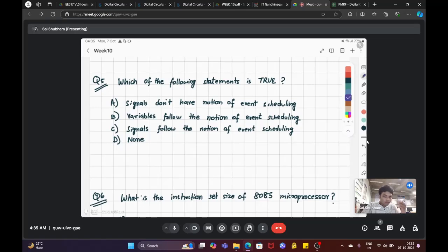If you want those operations to be iteratively performed over multiple cycles, you can use variables. You can define a variable i that is equal to 0 and iterate for multiple cycles. So in that case, there is the importance of variables. You cannot take a signal and iterate it because a signal cannot be iterated. You have to understand that signals have physical implications, whereas variables are in the virtual world.